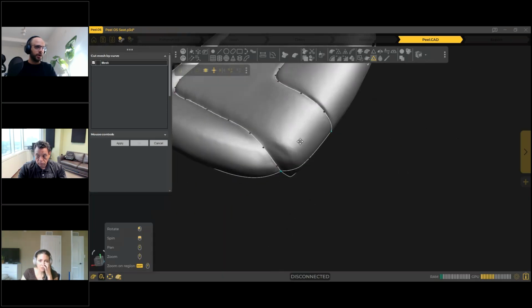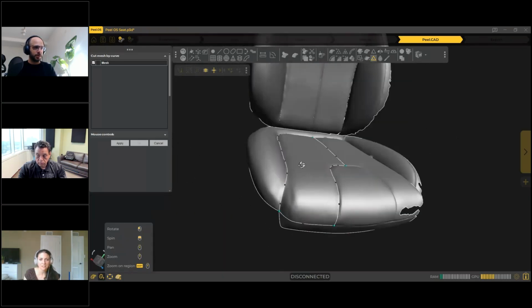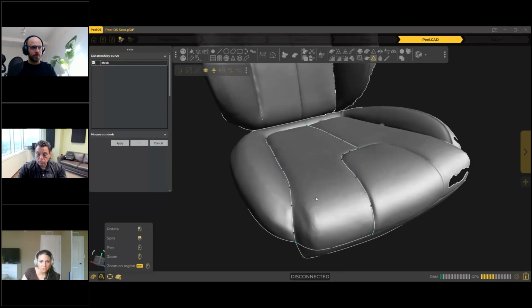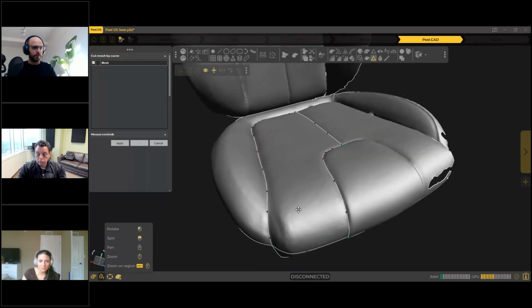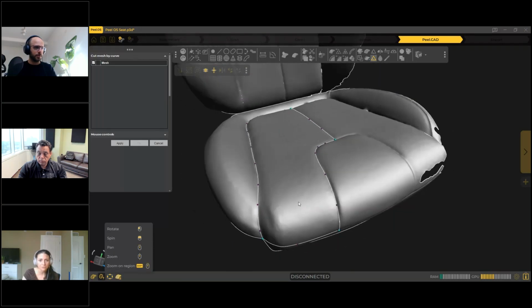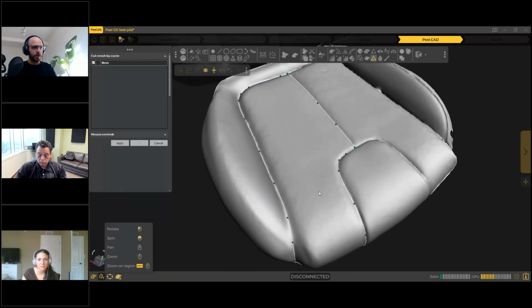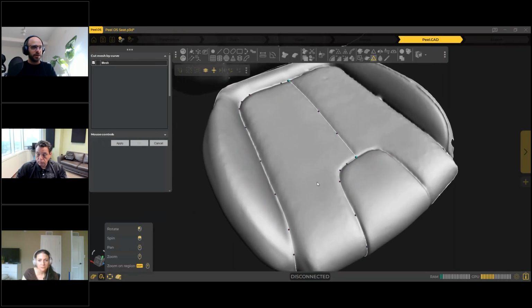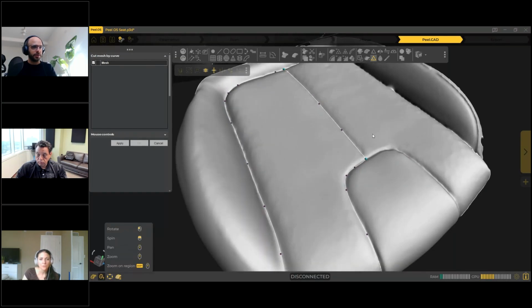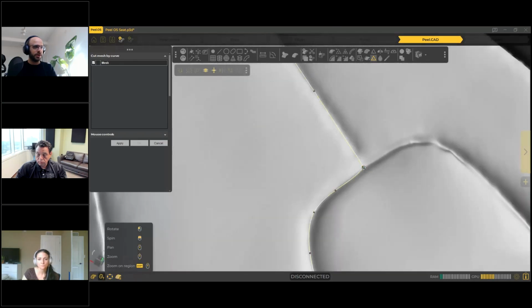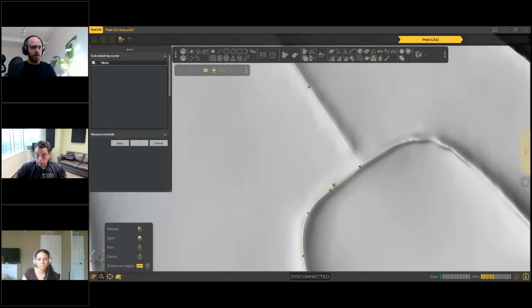So in this case, you're doing every little section, every patch, and I notice you're doing little blue dots on the corners, and then wherever you're curving, you continue with the little red dots. That's correct. When we double click, we create one of those blue dots. Those will allow us to create sharp corners.